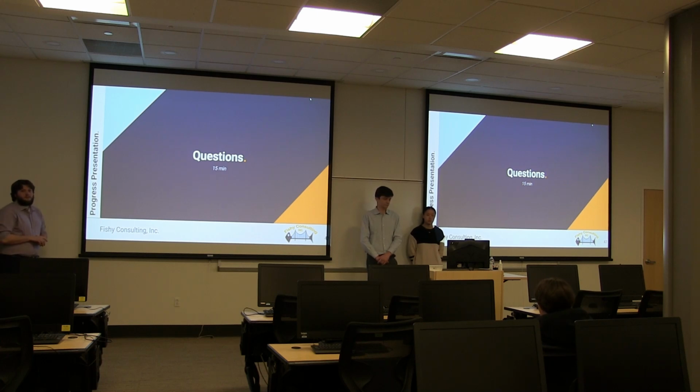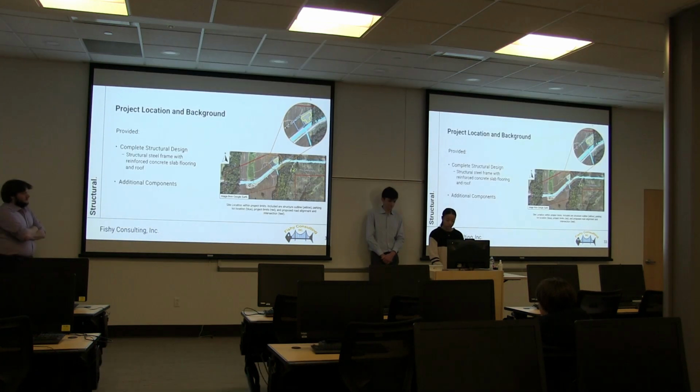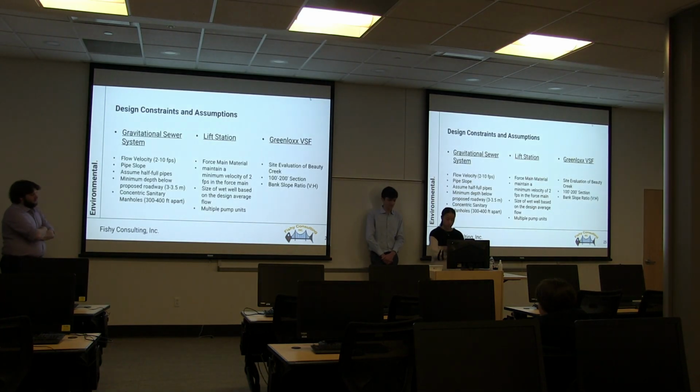Okay. Then on slide number 25, you're showing the minimum depth below under the sewer system, like 3 to 3.5 meters. Is that correct, or feet? Meters. It should be about 12 feet. Why? To allow for any potential construction for underground facilities. What? This was in the state standard.